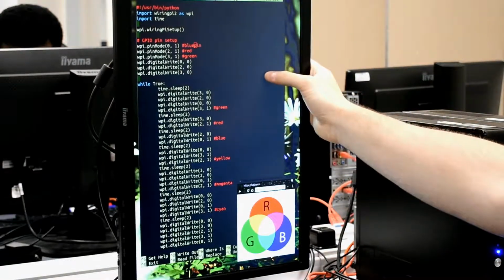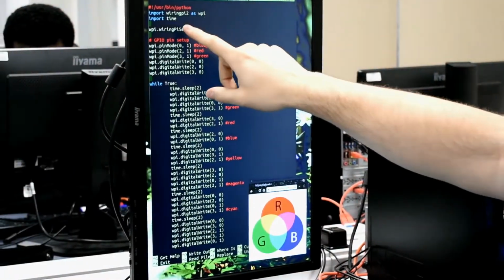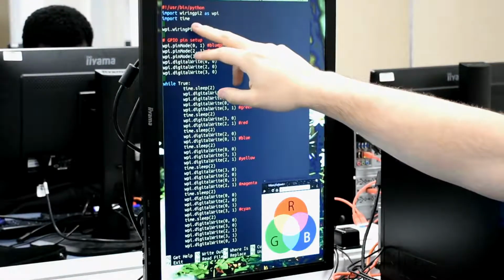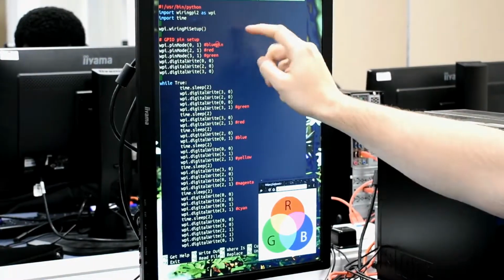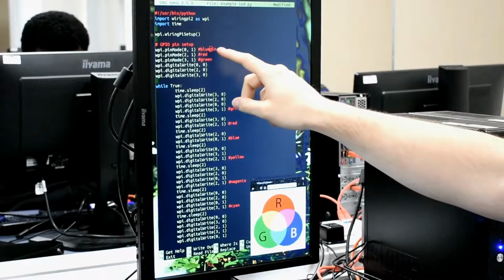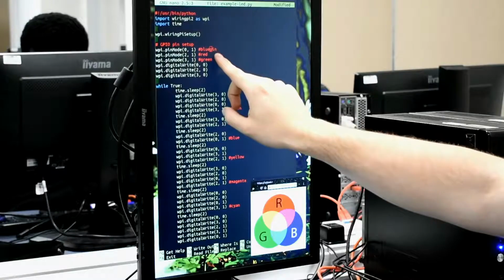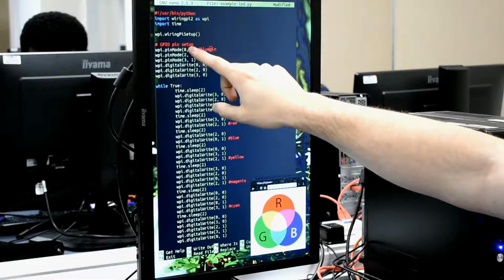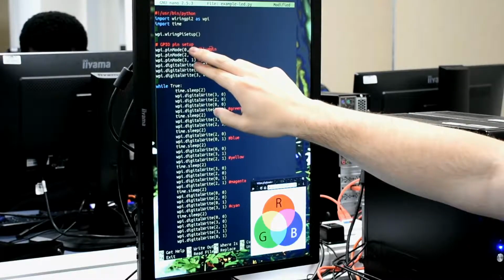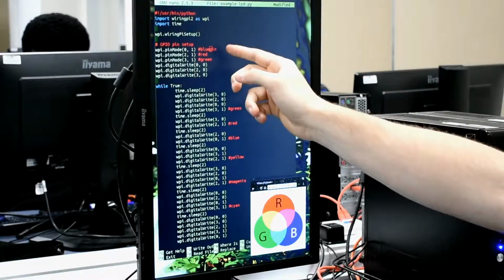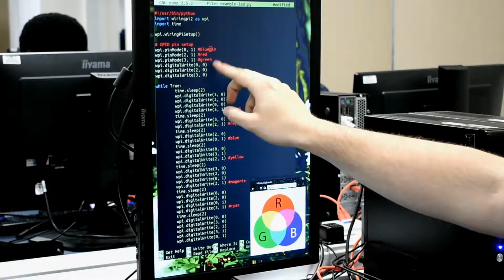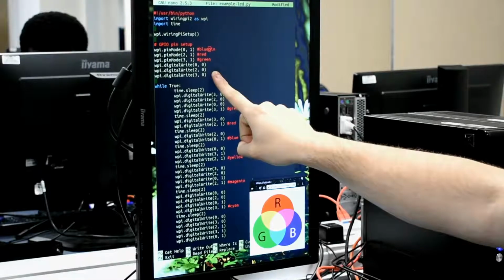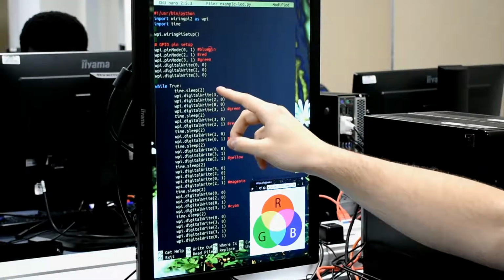So this is our Python script. We're using the WiringPi library, and we're importing the time module because we're using delays. Firstly, we have to initialize the pins, blue, red and green, from our pin layout that we got: 0, 2 and 3. We can set them on. We also set them to off when we start it up, so it doesn't initially stay on.